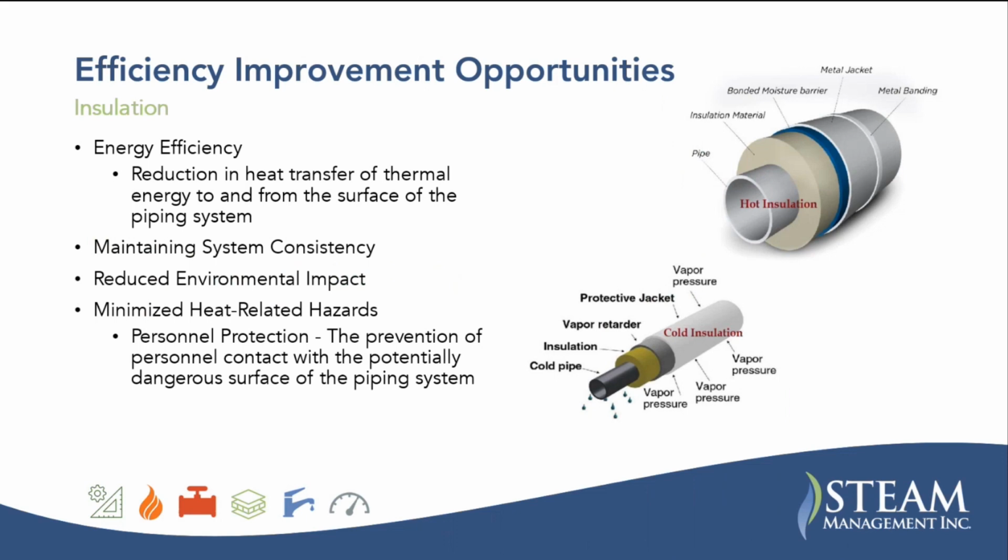So now we'll go into some improvement opportunities. So here's an obvious one, is insulation. So if you can keep your condensate hot, then you're conserving energy, which can be reused in your deaerator or your heat exchanger, or wherever you're recovering that energy from your condensate.